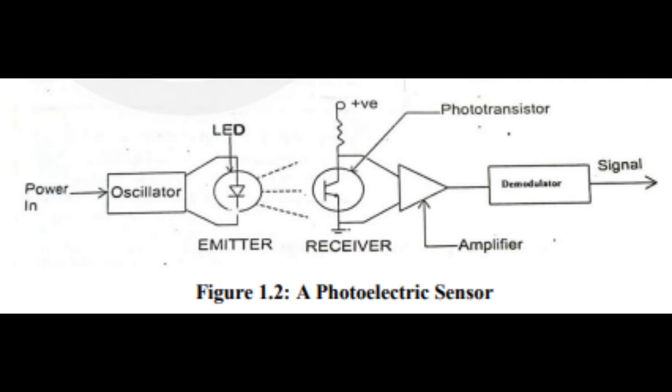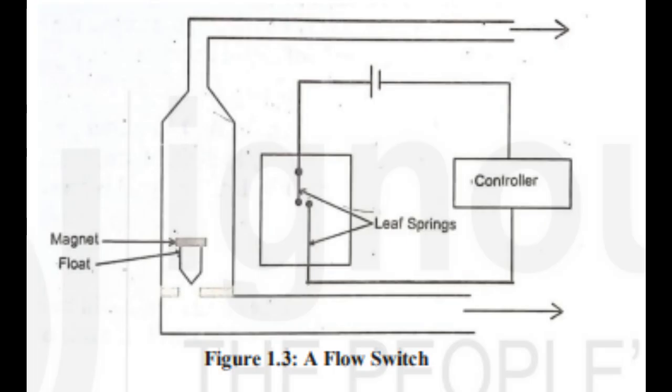There are different implementations of a fluid switch. One implementation is shown in Figure 1.3. Here a float is placed in a trapped column that is in line with the fluid flow. A magnetic ring is seated on the float and, in the absence of pressure, the movable float is retained in the seated position. Water pressure raises the float proportional to the flow rate. A switch is positioned at a height where the float will be displaced when the triggering flow rate is reached.